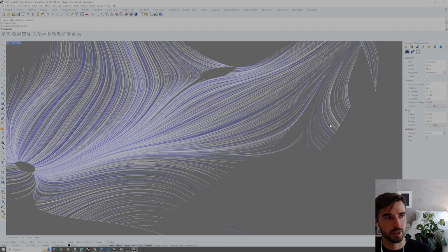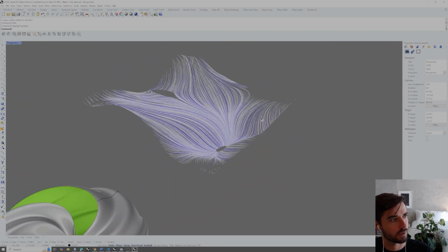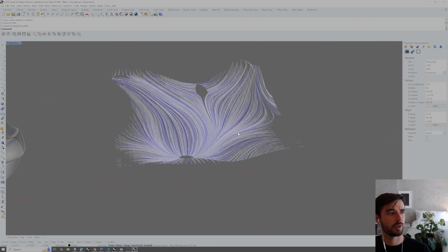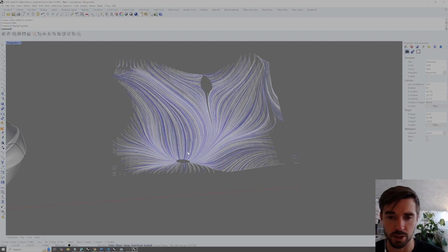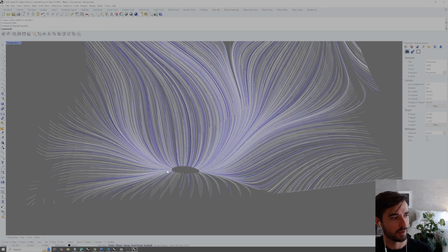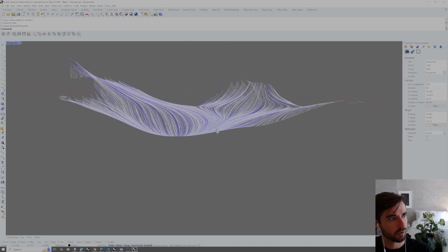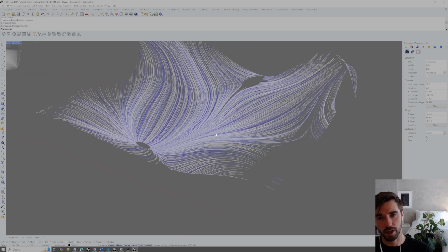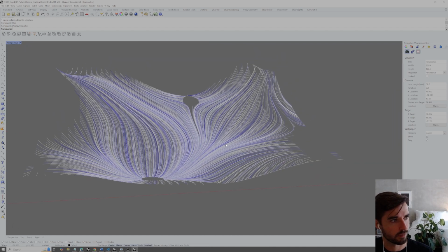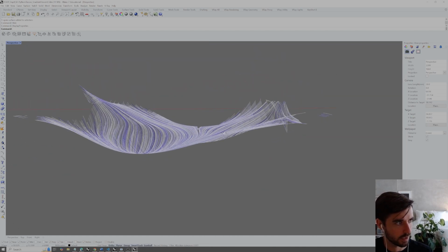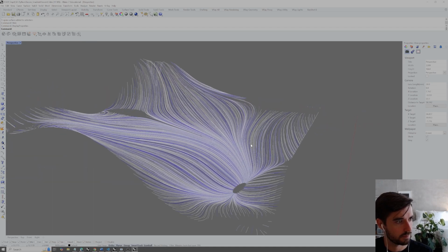So that is the simulated rainfall across our surface. We could even use this algorithm to make actual calculations or measurements based on random rainfall and the accumulation of particles. So we can make assumptions based on the properties of water or some liquid that's flowing across the surface, edit the mesh via erosion, or understand the amount of water or amount of fluid that might be collected in this particular surface.